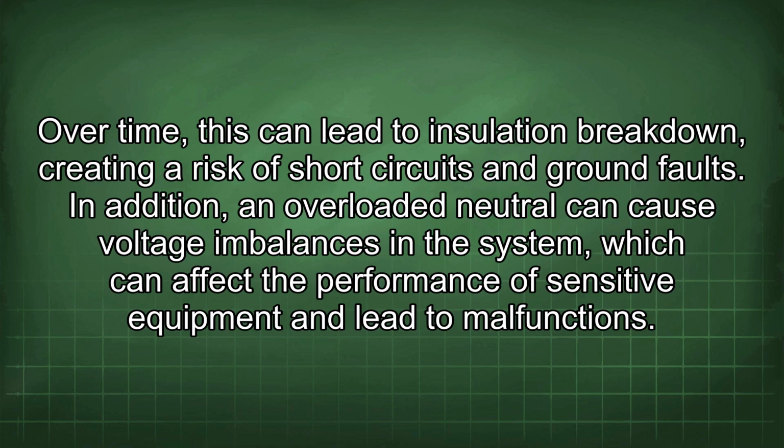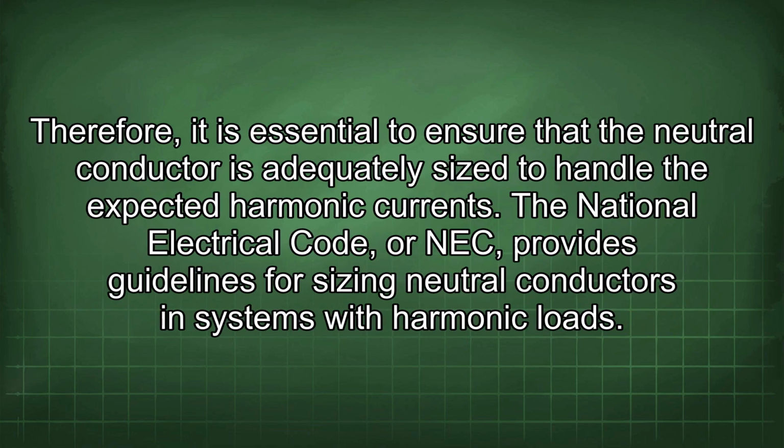In addition, an overloaded neutral can cause voltage imbalances in the system, which can affect the performance of sensitive equipment and lead to malfunctions. Therefore, it is essential to ensure that the neutral conductor is adequately sized to handle the expected harmonic currents. The National Electrical Code, or NEC, provides guidelines for sizing neutral conductors in systems with harmonic loads.